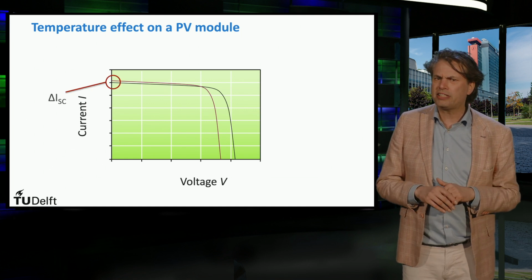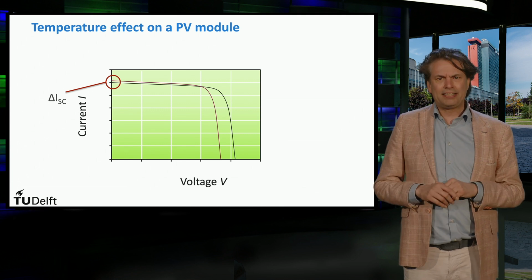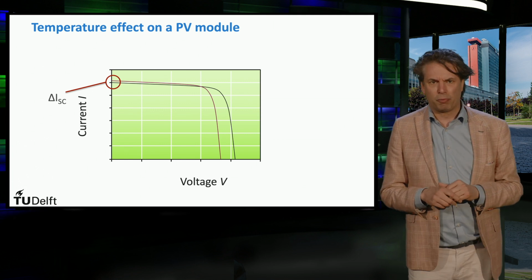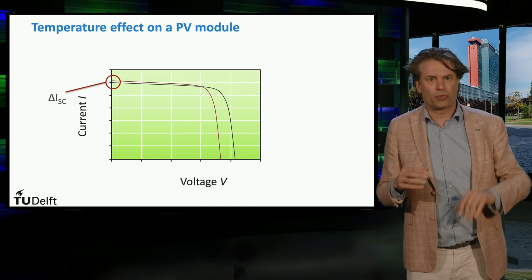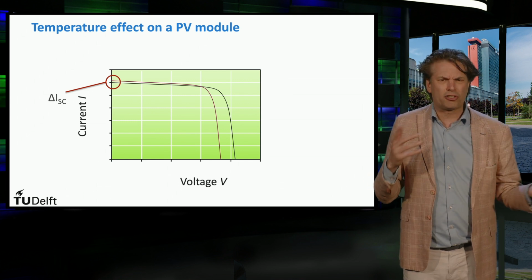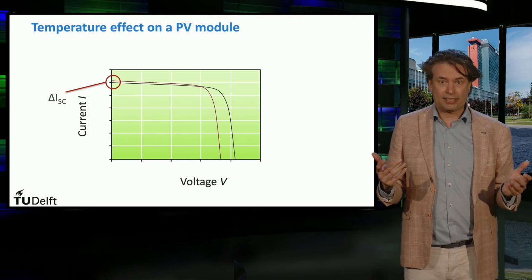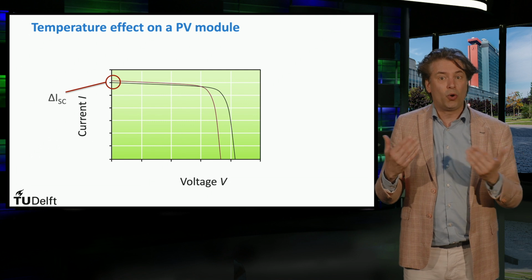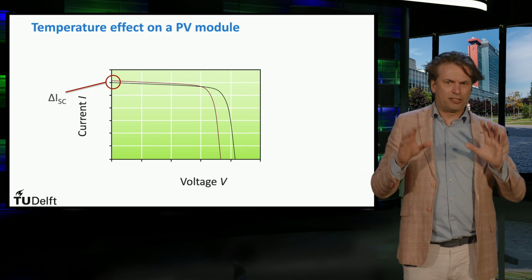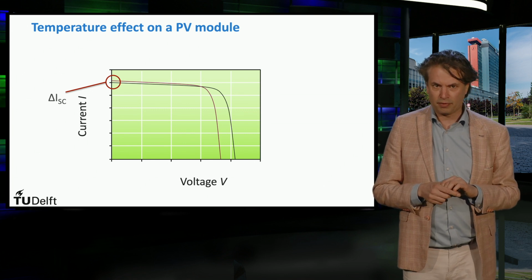The minute increase in current with temperature can be explained with the fact that carrier concentration and mobility increase in the semiconductor with temperature. This is consistent with our basic understanding that a semiconductor, unlike a regular conductor, exhibits better conductivity with increasing temperature and is a perfect insulator at absolute zero temperature.